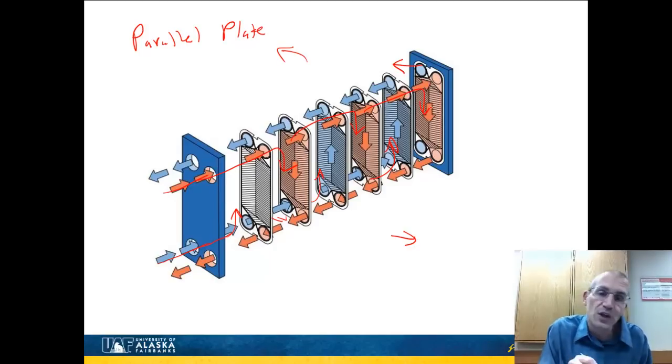And remember, in heat exchangers the fluids don't mix. And in the beverage industry, this is pretty important. You want to keep your materials sanitary against your cooling fluid. And so what's happening is transfer is occurring across these little thin plates. You can see it's occurring from that region over there and from that region into there, going from the hot fluid into the cool fluid. And each one of these sections is getting a little bit of the fluid.